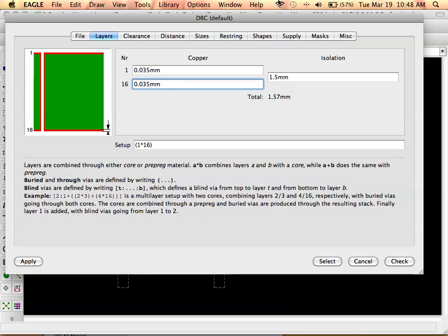Now that you can see you have some control over this, this is where we need to address the fact that you need to design for manufacturability, right? Depending on your needs, you might need more copper thickness on either the bottom or the top. As you increase that amount, that changes your design, the manufacturing needs and functionalities. It must meet with the board house.